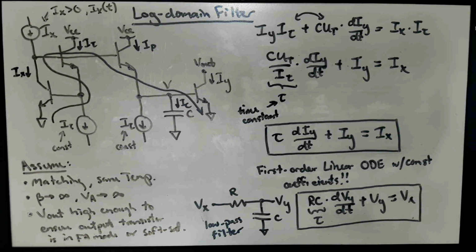They can get quite large. A typical on-chip capacitor, a very large on-chip capacitor, might be 100 picofarads. You can't really make a capacitor that's much bigger than that on a chip, realistically. So we typically will use capacitors that are kind of in the range of maybe a few hundred femtofarads to a few picofarads, or maybe 10 picofarads, something like that.